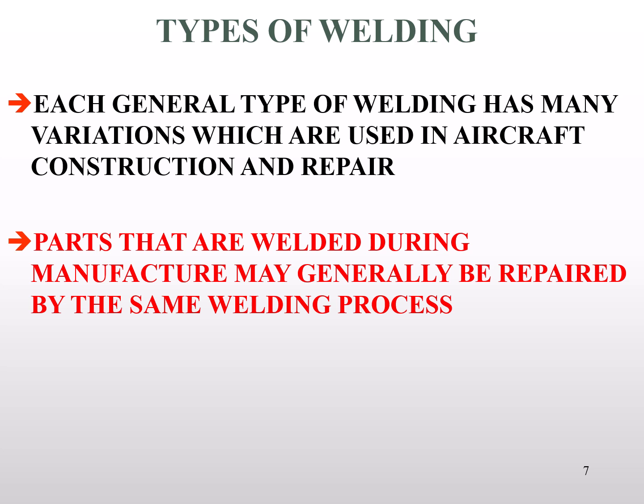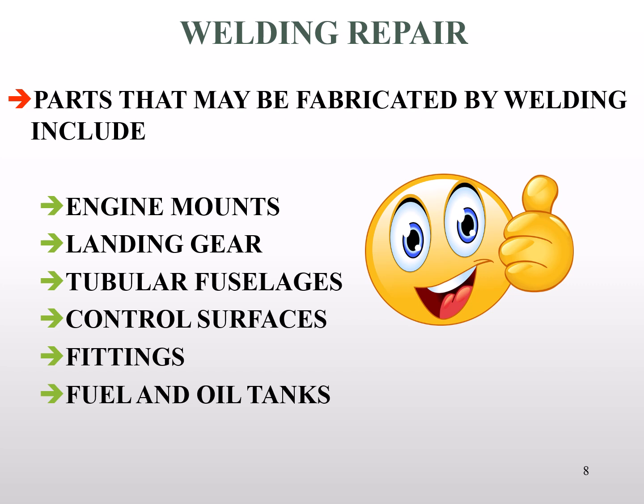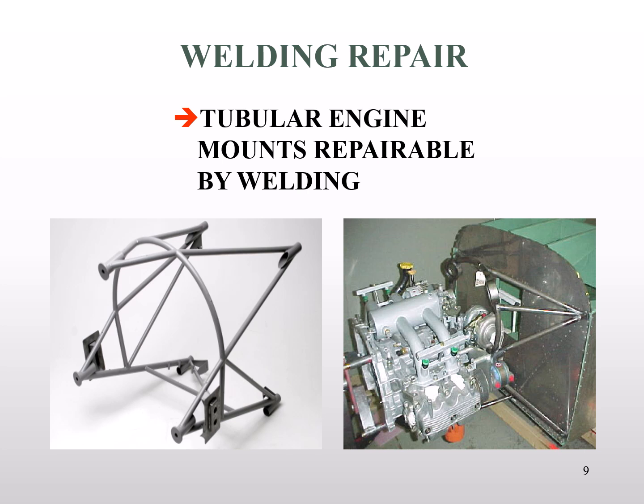Not all parts that were created with welding can be repaired by welding, but a vast number can. This is a basic list of typical welded repairs that could be made. Like I said before, there are limitations, but these are some that are commonly repaired listed here. Again, these engine mounts are typically repairable by welding. They were created by a welded method, therefore we can repair them using a welding method, assuming we have the material, the equipment, and knowledge to be able to do it.